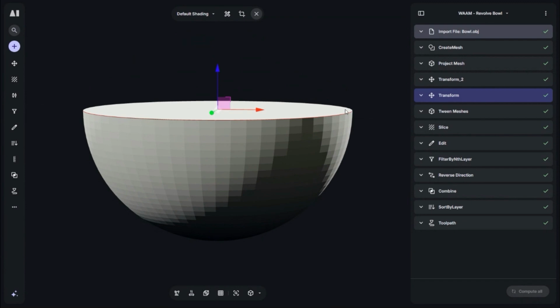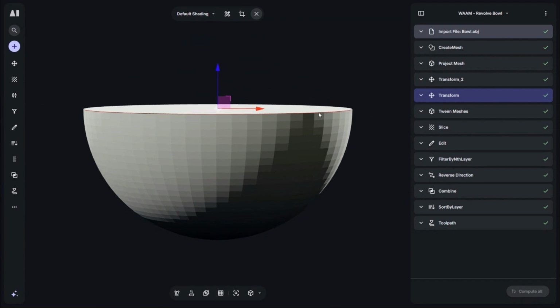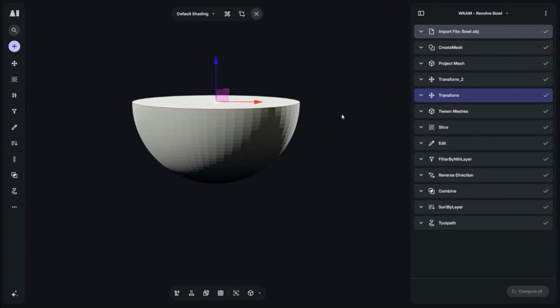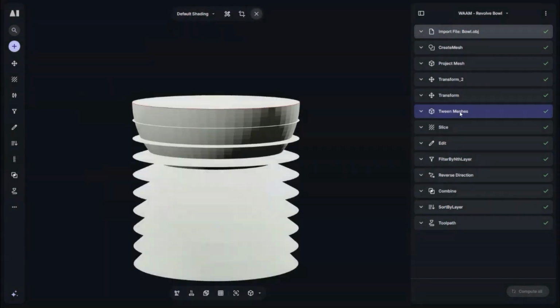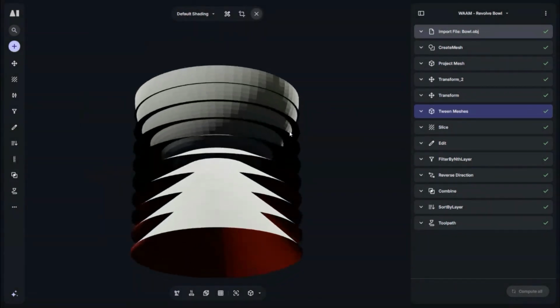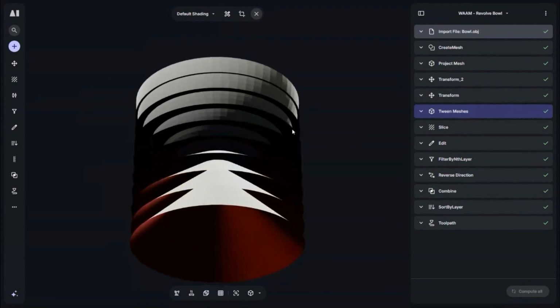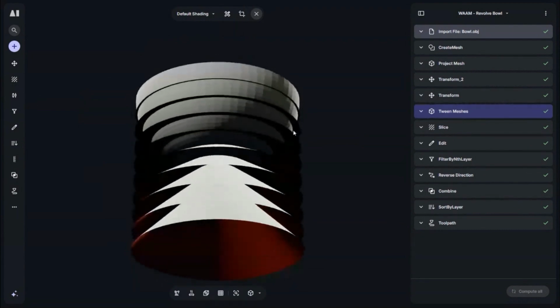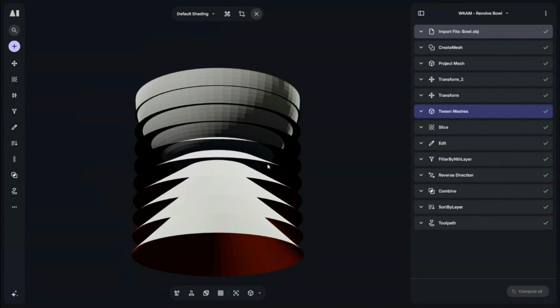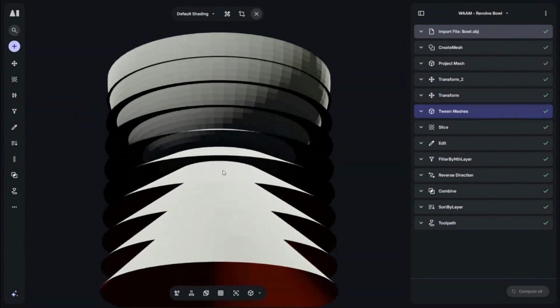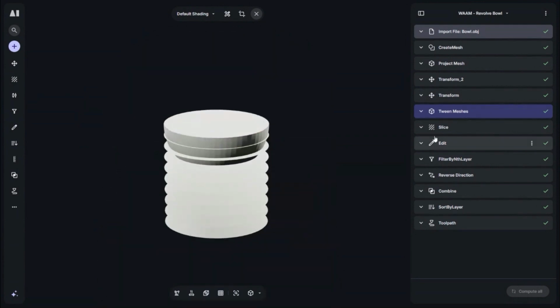It's just a flat circle, the shape of the bowl, so the layers at the top are going to be nice and flat. This is essentially how the non-planar slice works. It will tween these meshes as guides. Of course, much finer than this, but you can see how our layers are going to gradually conform to horizontal, and they'll start smaller here.